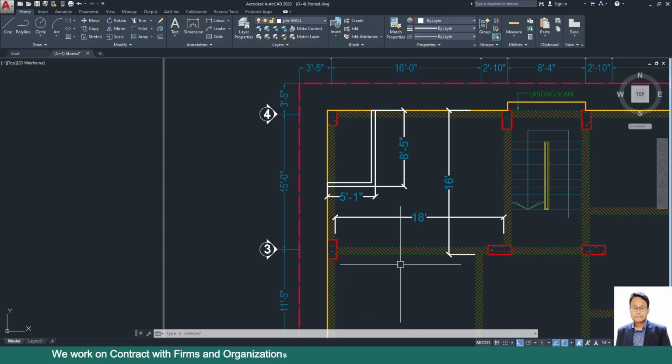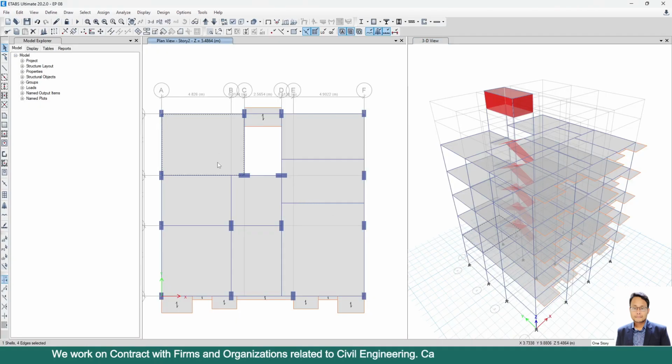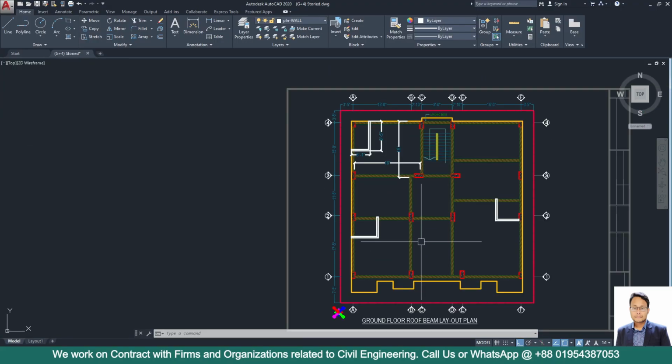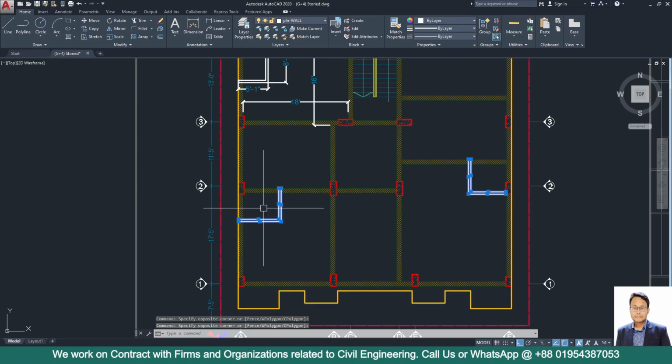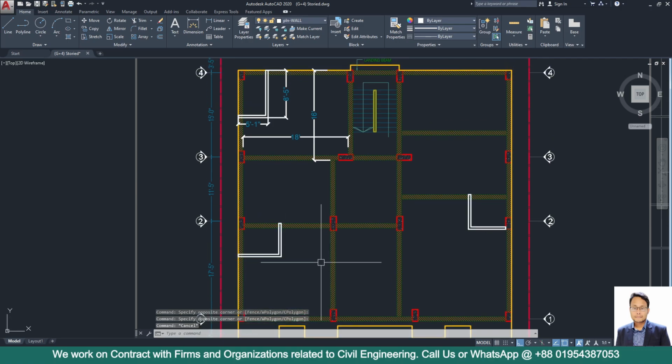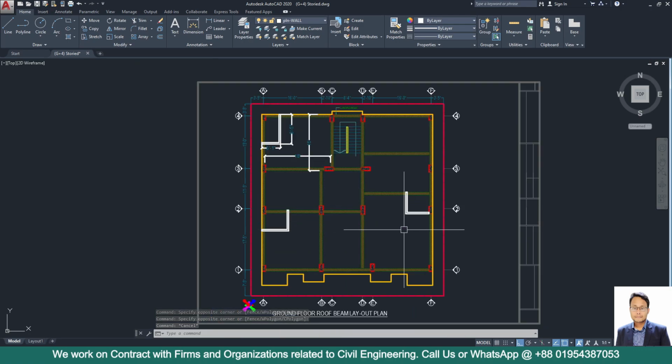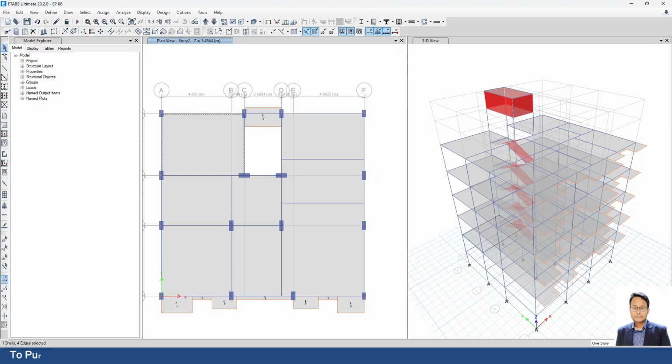Okay. So here I will use 2.37 kilonewton per meter square load for these three panels. You can calculate them separately and check the values. Okay, here I will go with 2.37. This panel, and this panel. Okay, so go to all stories.